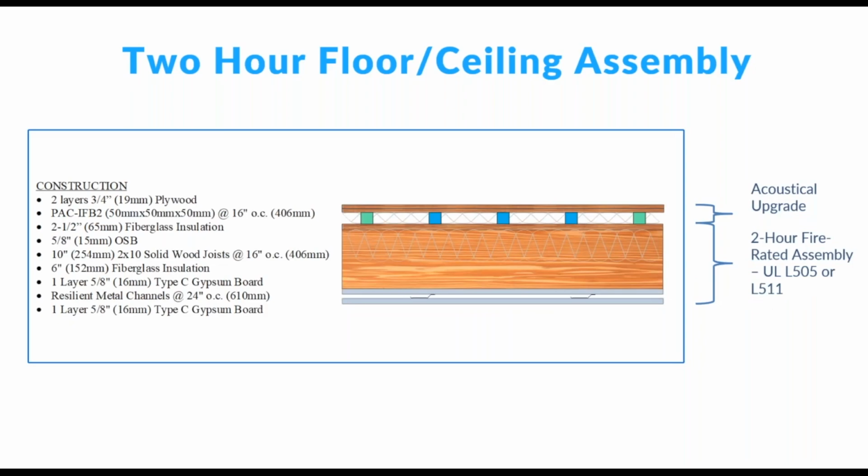Sometimes you might not be able to do anything on the bottom side. Maybe you're working with a tenant who's renovating that upstairs space and they don't have any control of what's going on downstairs. There you might use a floating floor. And again, it's not part of the fire rated design, but it's the acoustical add-on.